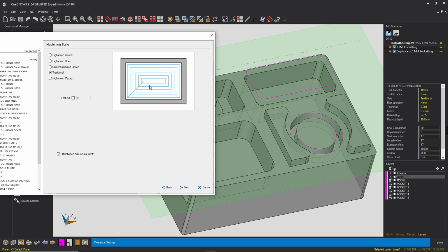But a lot of the time your traditional style step over is going to be way faster, and if you're doing it on aluminiums and stuff where your tool life, I'll be honest, with modern day carbide tooling and coatings that they supply now, traditional cutting is just fast.